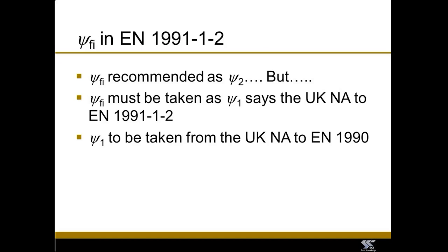We've got the option for psi fire in EN 1991-1-2. The Eurocode itself recommends that we use psi 2. But here is a really important intervention by the UK National Annex, because in the UK, our National Annex says, no, no, no, psi fire should be taken as the value psi 1.